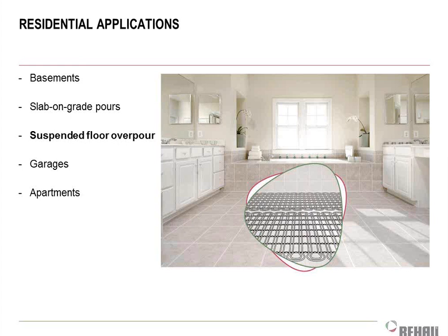They got these little nubs, I'm going to call them, and you can use those nubs to kind of wrap and wind your radiant tubing around them. The other mechanism is to use some kind of foil-faced insulation, and we use some here, and we lovingly call it bubble wrap, right? Because it looks exactly like bubble wrap that you have for packaging purposes, but it has a foil-faced insulation on one side of the bubble wrap, and you face that foil so it points upward, and then you put your flooring system on top of that, right?